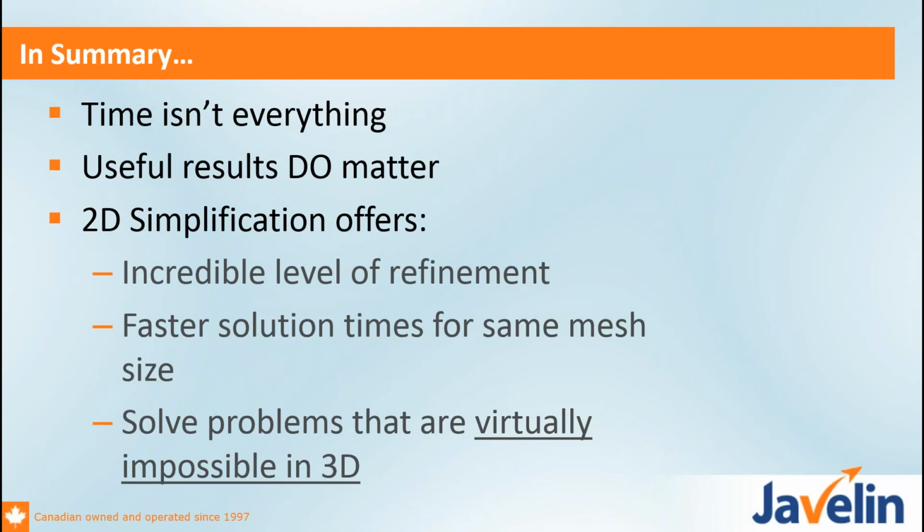But 2D simplification really offers some great benefits, an incredible level of mesh refinement, much faster solution times for the same mesh size, and like we just showed, we can solve problems that are virtually impossible to solve in 3D just due to mesh limitations.